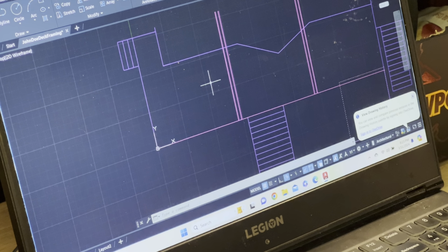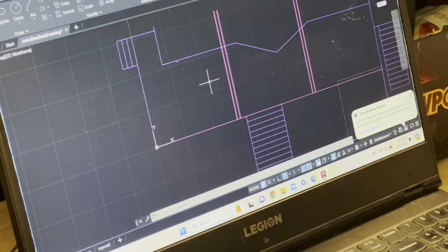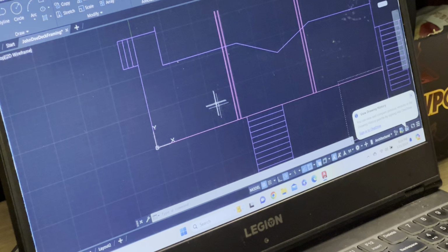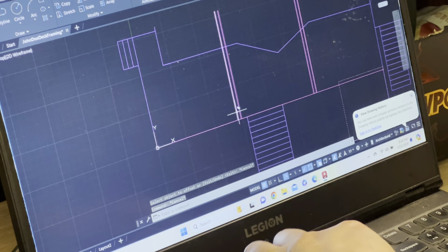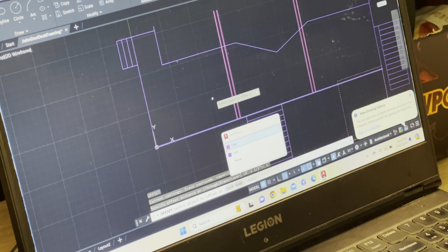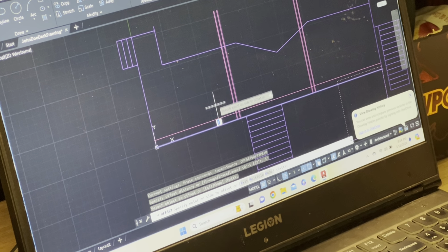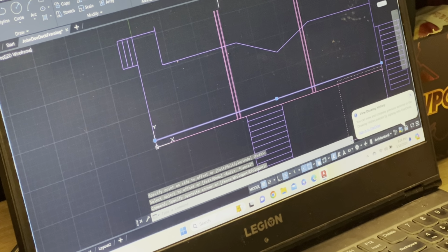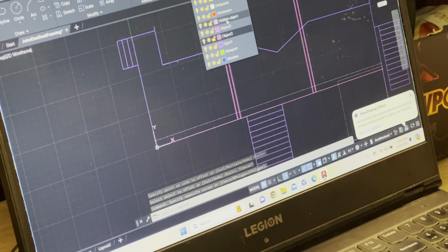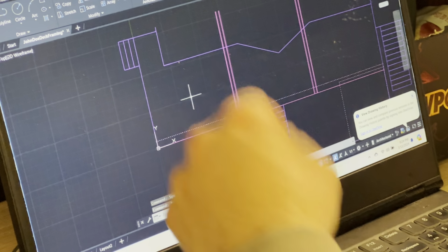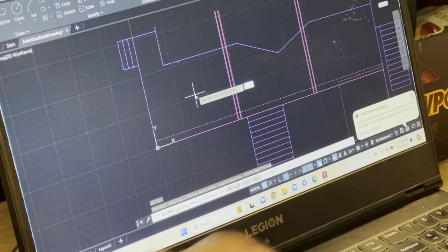That's center of post to center of post for my beam span down here, right? I'm going to have one beam down here somewhere, and one up there somewhere. I can establish this one right now by going offset 1 foot. And so I don't confuse it, I'll make that a hidden object because that's the edge of my beam down there. And then I'll go offset 10 feet.